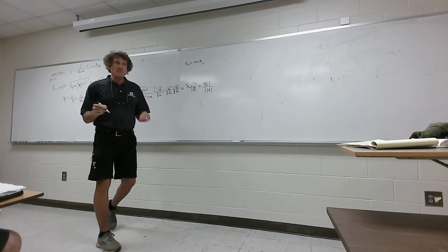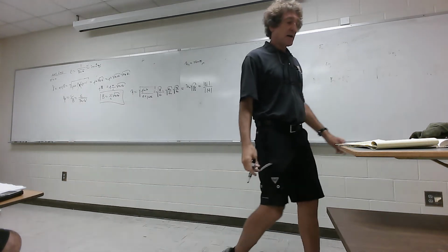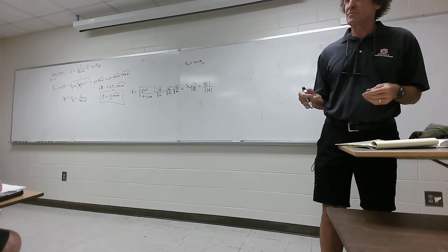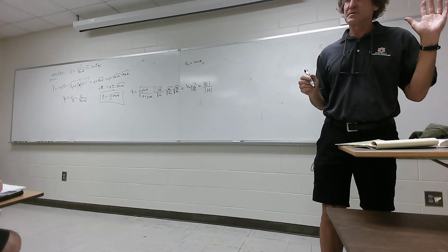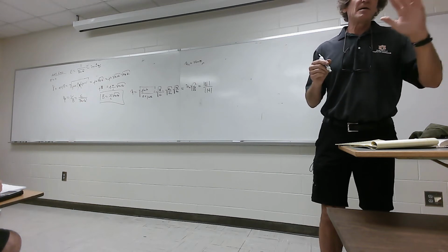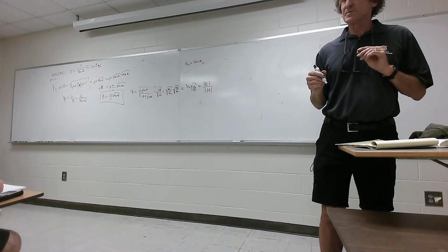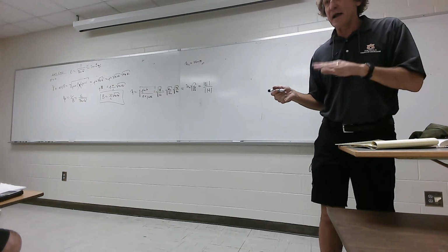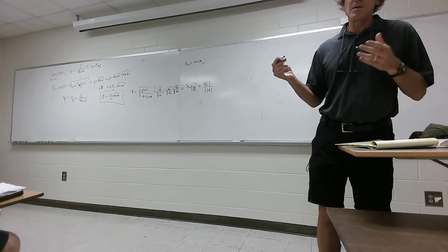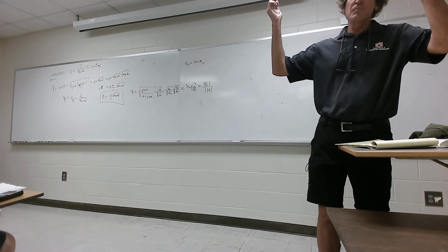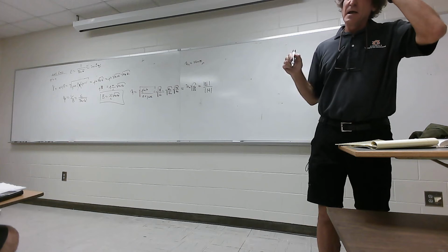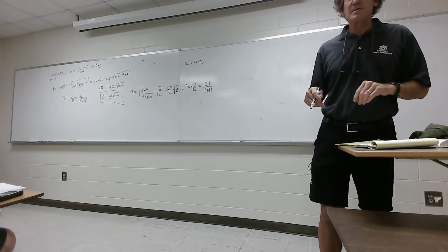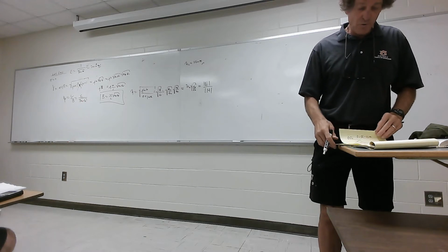Alright, the next part, it's fairly easy. You just have to realize that if you have a mu relative, epsilon relative, and sigma 0, there's no loss. The velocity scales down as a square root of epsilon relative and mu relative. The intrinsic impedance actually goes down by square root of epsilon relative, but it increases with square root of mu relative, if you take a look at that. And the phase velocity, it just slows it down, basically. But that's the thing you need to worry about.